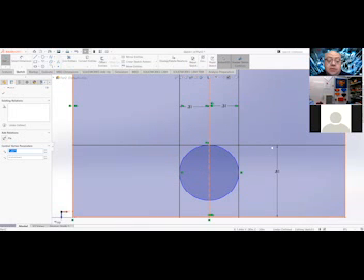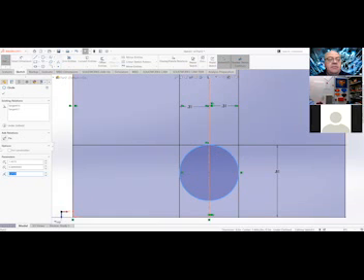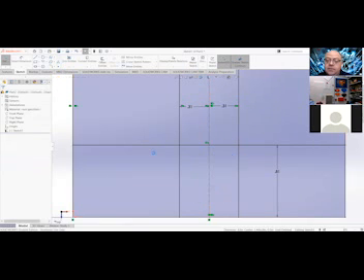I'm going to delete this circle now, and I'd like you to do the same, and we'll then do it a different way. So if I select that circle, it's going to tell me a little bit of information about it, some of it good, some of it bad. What it does tell me over here before I delete it is that my radius is 0.3125 or 5/16. We already kind of knew that, right? It's what we did for our offsets. So when I hit my delete key and the circle's gone, I realize I've got 2 lines and a bar that I can do something a little bit more with, okay?